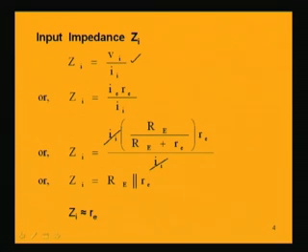So, what we are left with is the input impedance, Re by Re plus small re into small re, and that is nothing but the parallel equivalent resistance between Re and small re. So, we now have the input impedance as the equivalent impedance between the two parallel impedances, capital Re and small re.